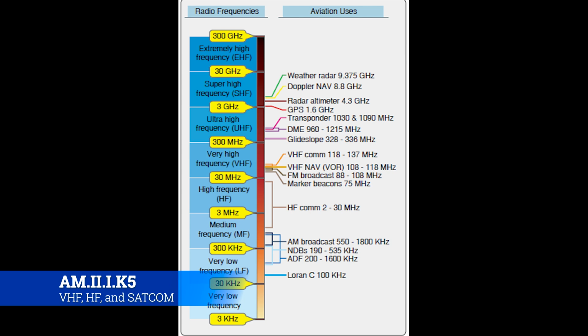Then you go to another station, and I'm 75 miles from this one, so you adjust your compass to match the scale on the sectional, draw another circle, and eventually you get this Venn diagram effect where the only place you could potentially be is in this little narrow band. The more DMEs you have, the more you can tune into, the more accurate you can make your position. So that's what it is.